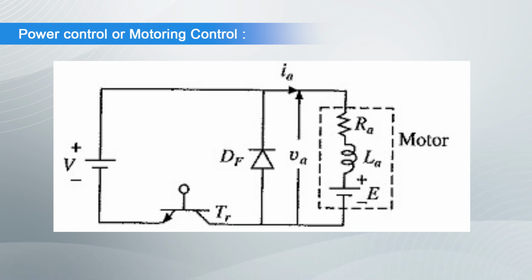The figure shows the basic arrangement of a DC chopper feeding power to a separately excited DC motor. The chopper shown consists of a force commutated thyristor. This drive generally offers one quadrant drive operation.